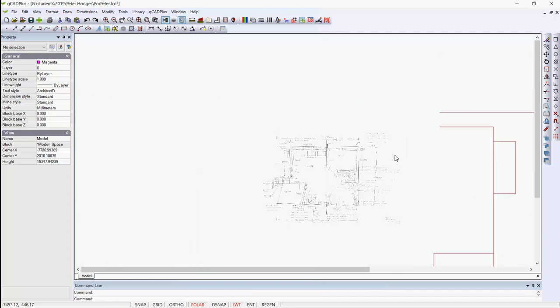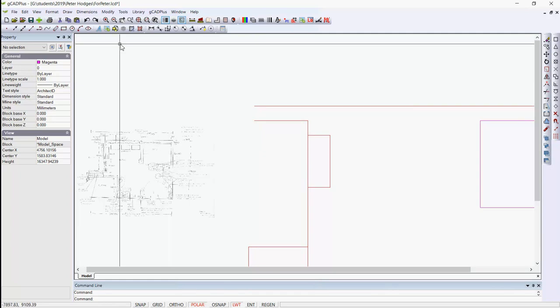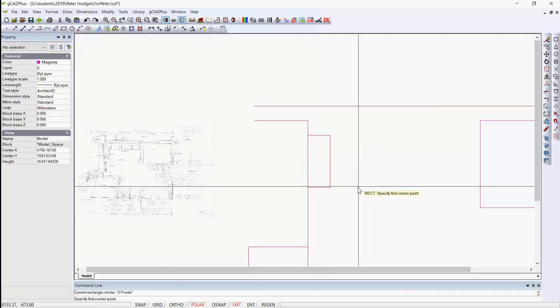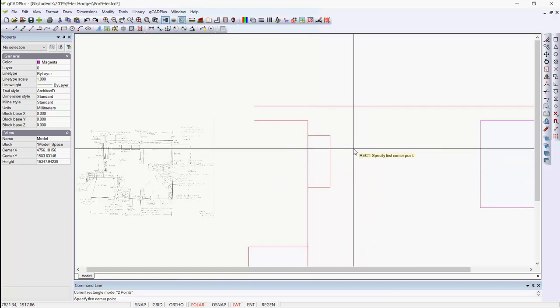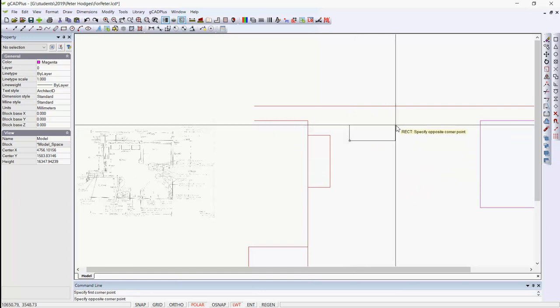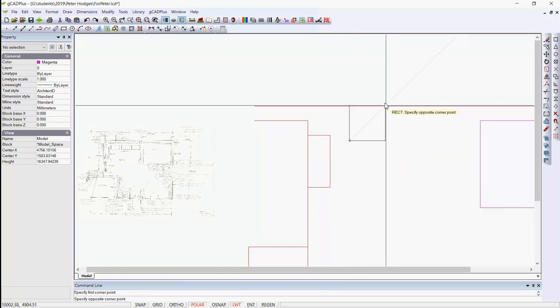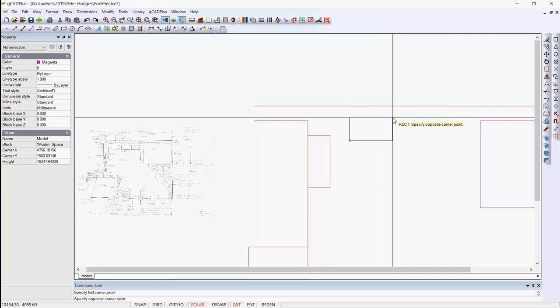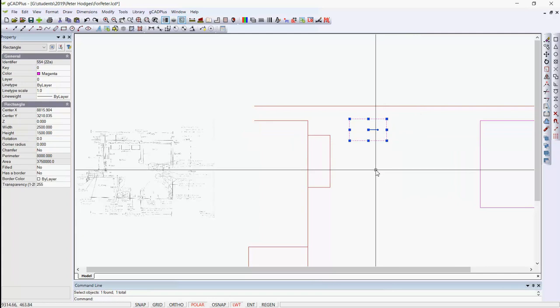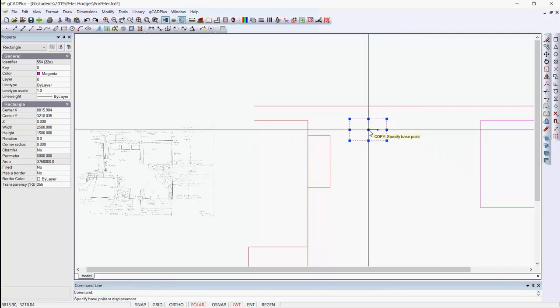We'll zoom out and just pan across to the space where they go. Draw rectangle, 2 points. First corner point, we'll start in approximately the desired position, which is about there, based on my mud map, and then I'll introduce a new way of working. It's the at sign, and it's for relative coordinates, so at 2500, 1500, and that puts the rectangle representing a raised garden bed in place, and we can copy it from there